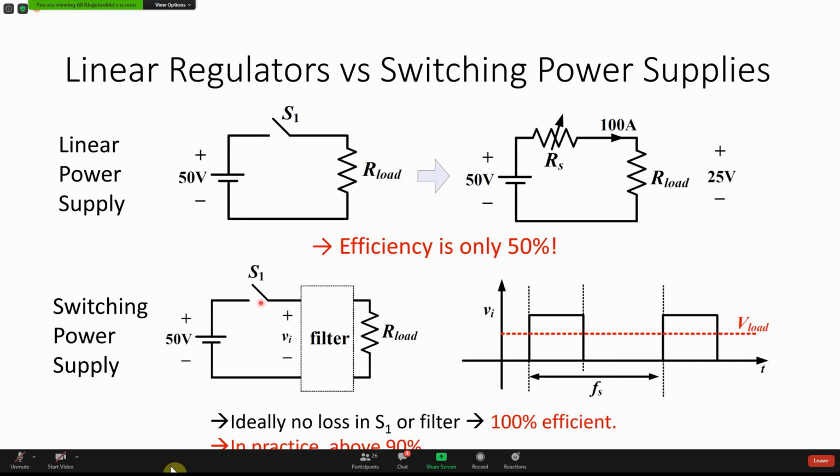So the on-time losses, the on-time resistance can be fully on, right? The fully on resistance can be like milliohm, and the fully off resistance can be hundreds of megaohm. So you don't have any losses. But here, because I was working in a linear region, I had to get something between, not milliohm, not megaohm. I had to make that resistor exactly equal this load resistor to get half of the voltage. That's why the resistance here was not something that I could avoid.